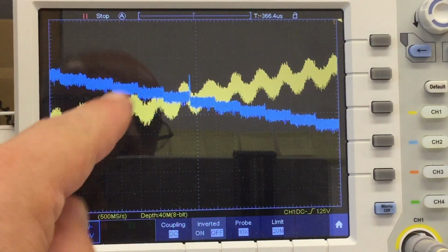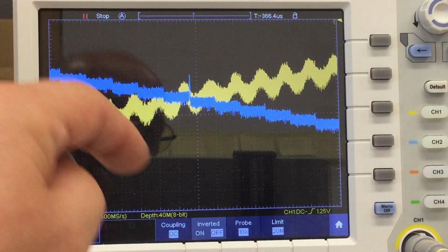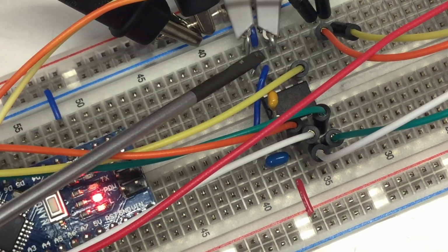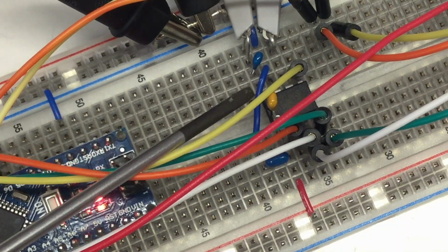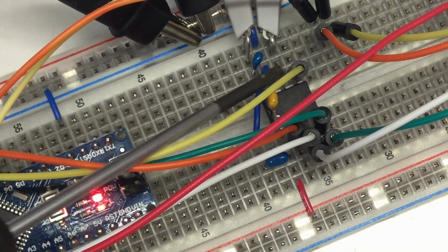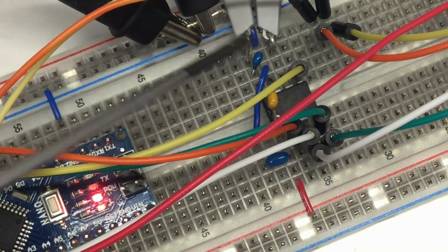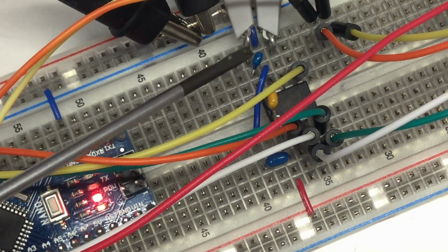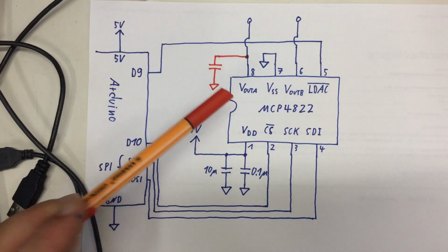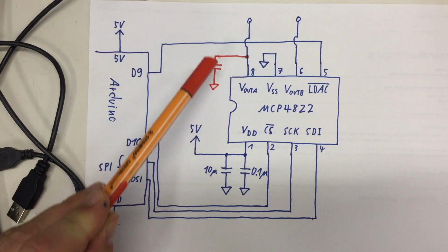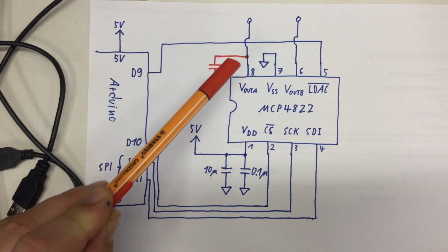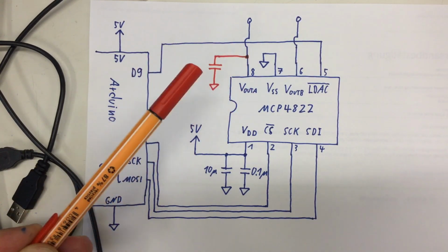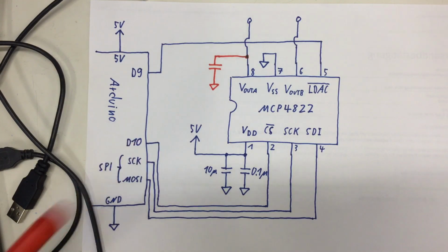Anyway, let's have a look at the schematics and at the breadboard. And there it is, my 1 microfarad ceramic output capacitor here between my ground rail and my channel A output rail. To make things very clear, here's where I placed that capacitor, on the Vout A pin to ground, and yeah, not working.